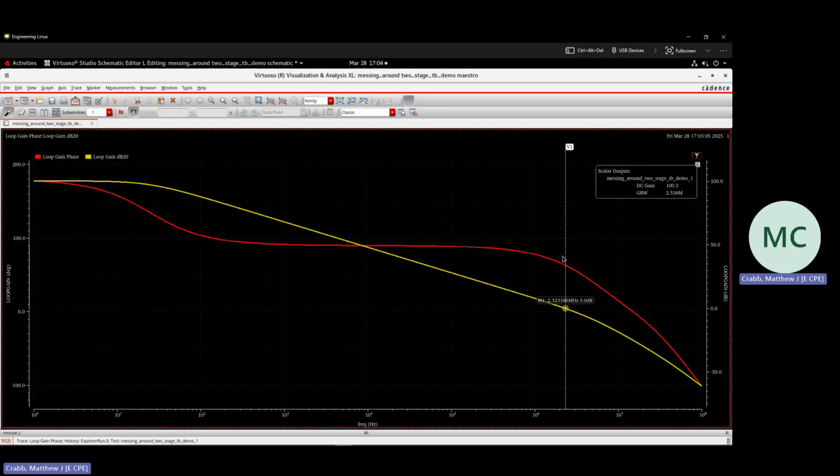that to read our phase margin, we want the amount of degrees we're above a negative 180 degree phase shift. So in this case, a 180 degree phase shift, it can go from 180 to 0. So we can just read this right off the marker here, and that's our phase margin. If that doesn't make sense, review classical control theory.